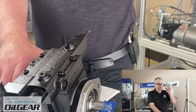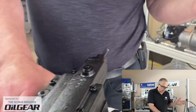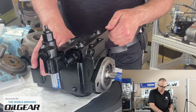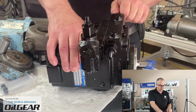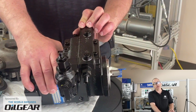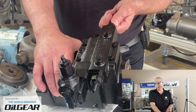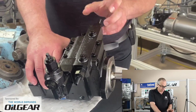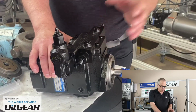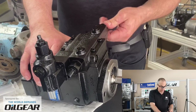It's not an everyday common value to be dialed in, but we do encounter it on steering pumps, on some mobile equipment where it is desirable to still have some flow definitely coming out of that pump even when fully compensated, which then does definitely require a system relief valve to be present in parallel with the system for protection. Okay, so that's what that is. That's a minimum volume stop, Q minimum.